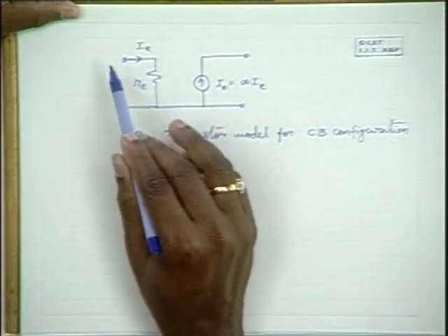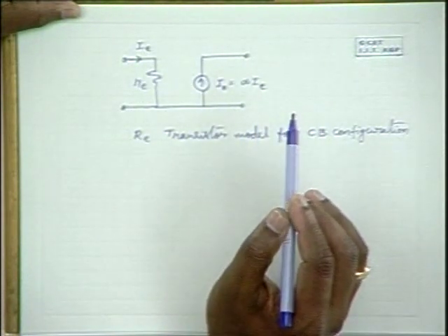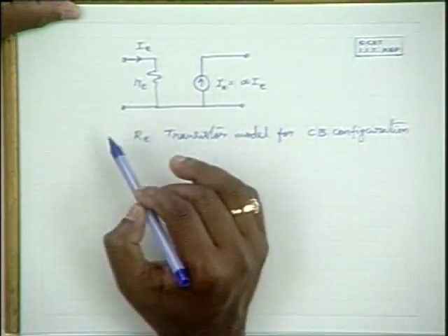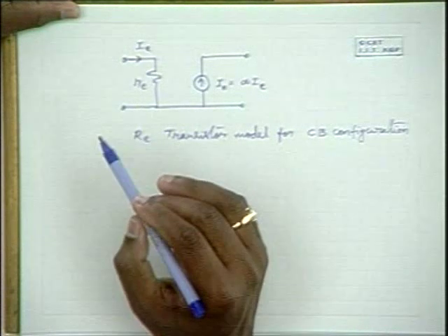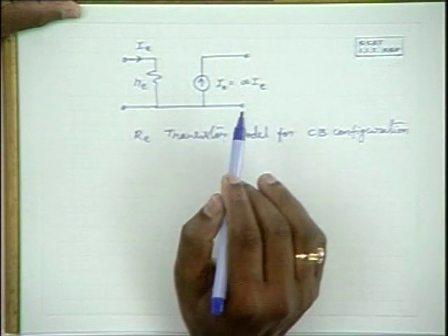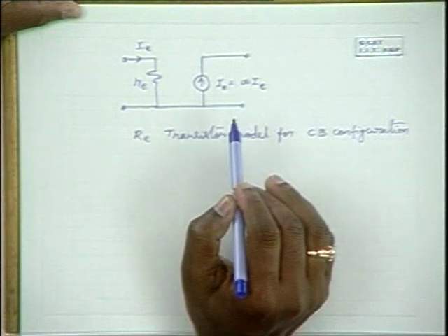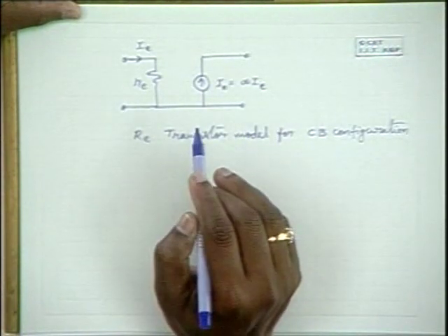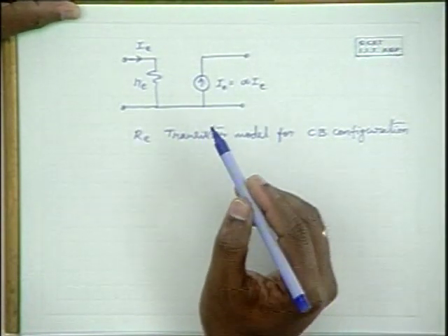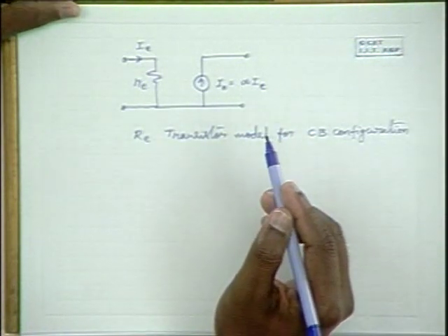So including all these resistances, it becomes a transistor amplifier circuit. Now, when you introduce all these resistances in the circuit, how much is the gain it offers, and the input impedance and output impedance it offers are to be determined. To determine that, you can use this model for the transistor. The transistor can be replaced by this model, and simple Kirchhoff's voltage laws and current laws can be used to analyze the problem and determine the quantities of interest.